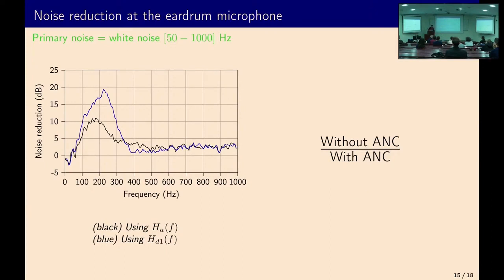So you see that for both cases, we have noise reduction on a quite reduced frequency band, but it is a bit higher for the digital filter, and it is what I said before, the gain margin is better, so we actually get a higher noise reduction. But what is more interesting in our case is when we want to broaden a little bit the frequency range of attenuation. With the series of two backward filters, we get higher noise reduction and a broader frequency range.